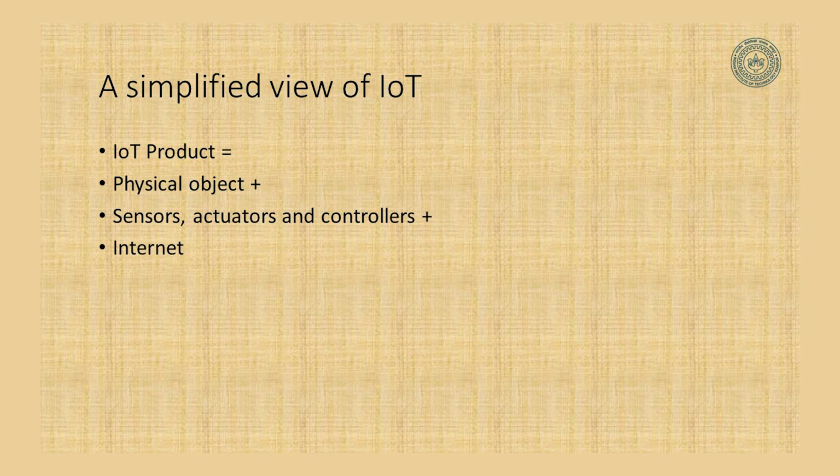That is what all of you will be doing in your project as well. Something to think about: many of you have given bills of materials where you have mentioned the controller that you want to use, and you have suggested you will use the Arduino board, but the Arduino board generally cannot directly connect to the network, you will need some Wi-Fi add-on.